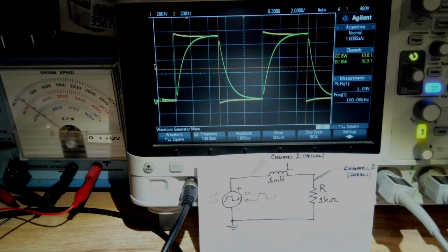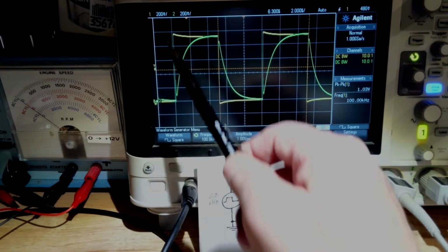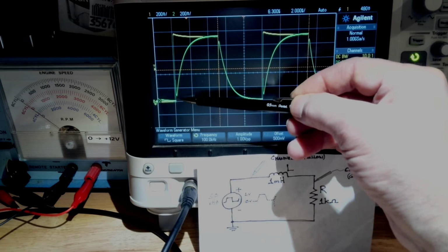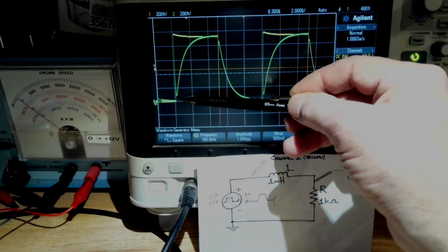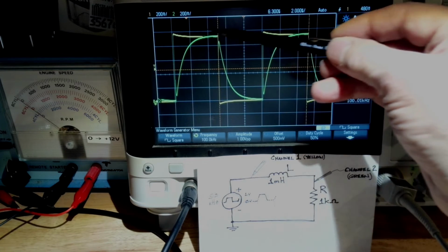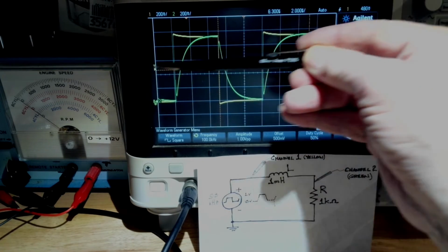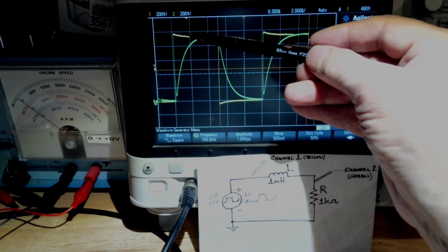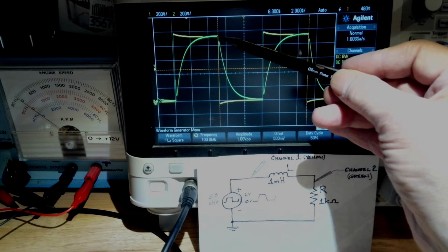And it goes to a very simple rule, and that is to say that current lags behind in an inductive circuit. Notice here, the voltage snaps immediately, okay? See how the voltage goes right up? The current lags behind because things to the left are earlier. The voltage snapped right up. But the current took later until it built up to what the voltage was.